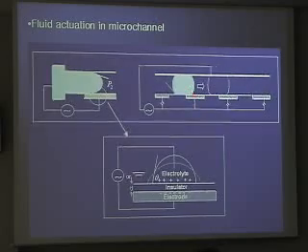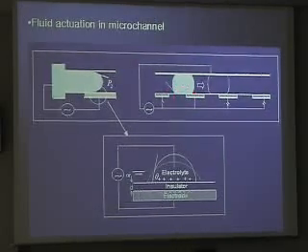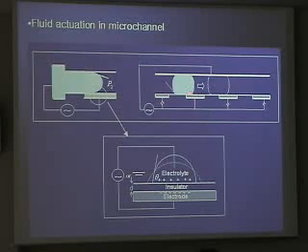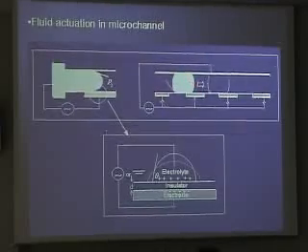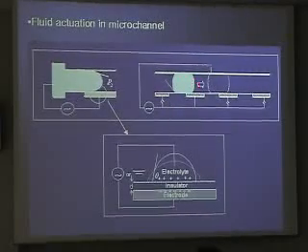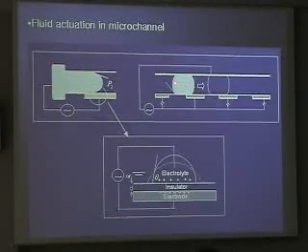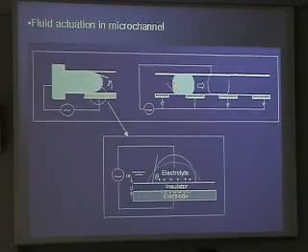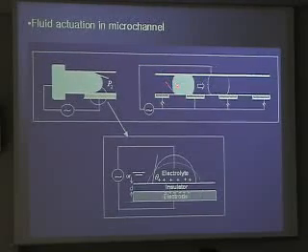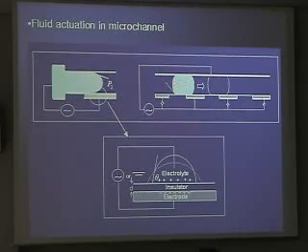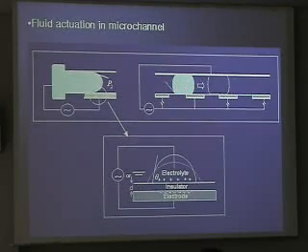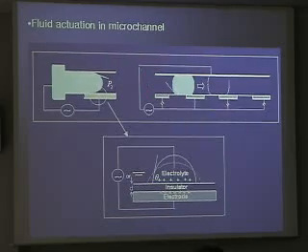Here electrowetting occurs and here not. Then the contact angle here is smaller than the contact angle here. That means the same pressure here and here, but the pressure here is a little bit higher than outside. But in this situation, the pressure inside is much higher than this. So inside the drop, we have a pressure drop, a higher pressure region and a low pressure region. That's why this drop moves in this direction.